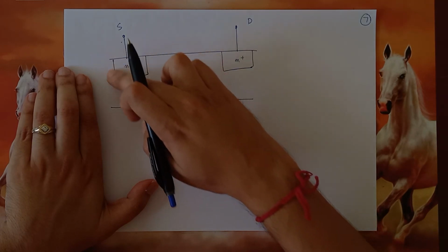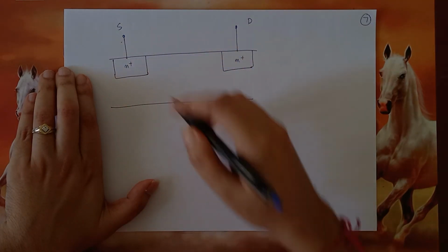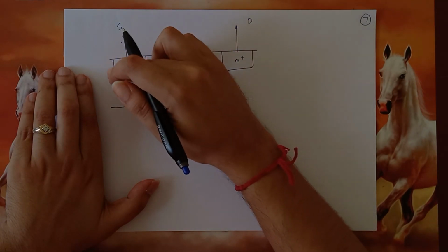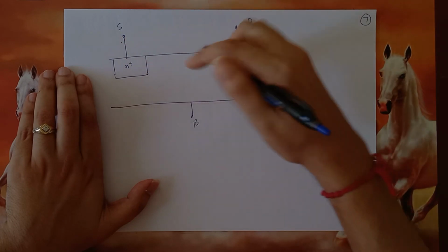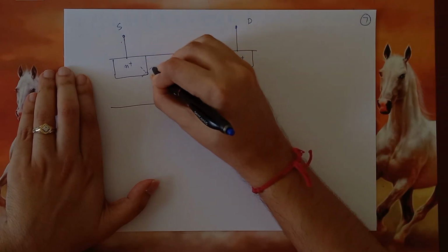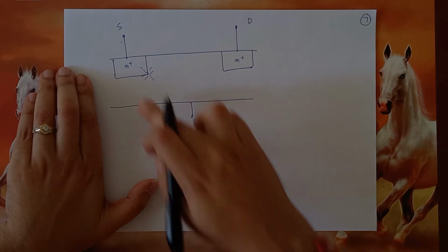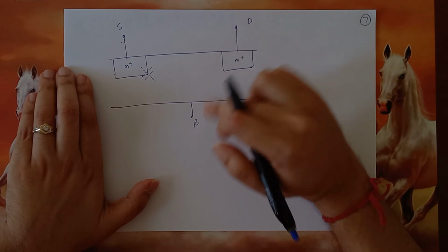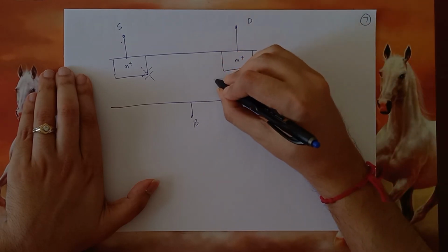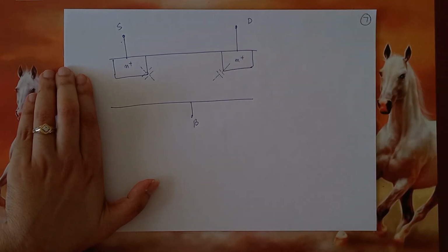So when the body and the source are reverse biased, what will happen is that essentially there will be a capacitance that exists between this junction, because this will now form a depletion region. Likewise, if the body and the drain is reverse biased, there will be one more parasitic capacitance between these two.